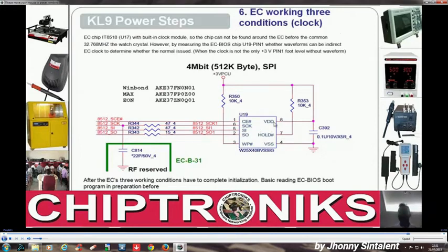You see, this SPI chip, this flash BIOS, is connected to the plus 3V PCU, which is already generated. So it can read this BIOS, and we can read the data through an oscilloscope. If there is a valid data waveform over here, and we'll see how that waveform looks, then this process is okay.